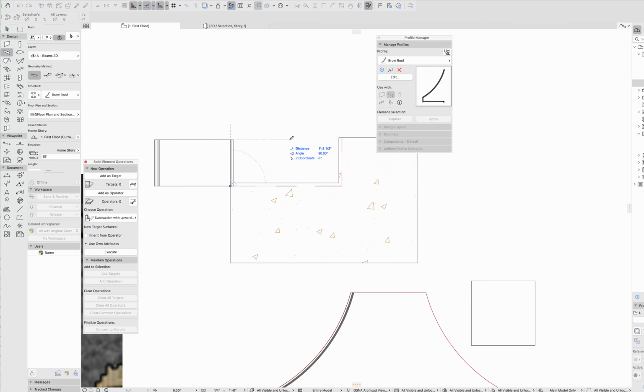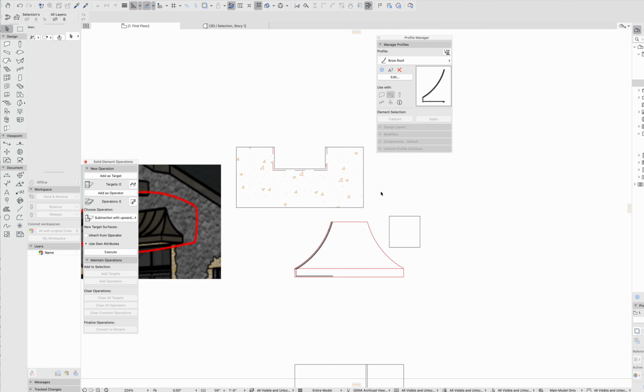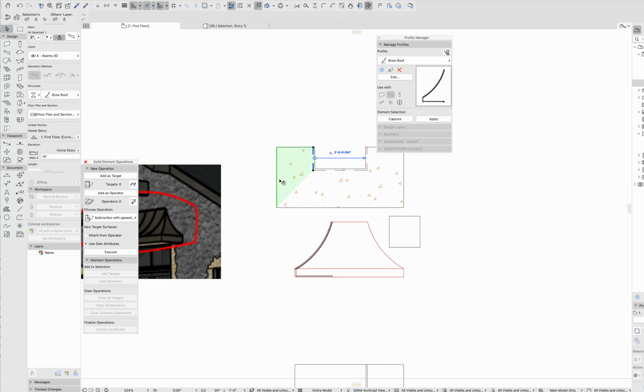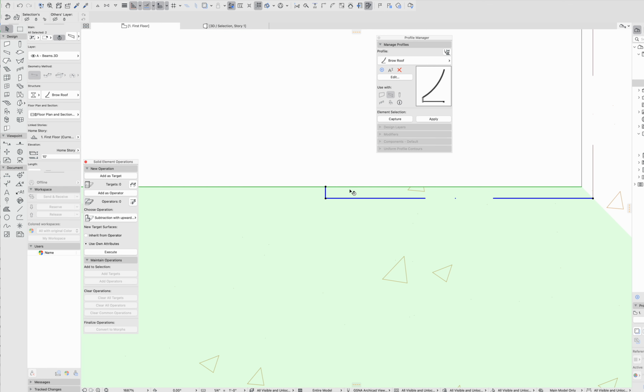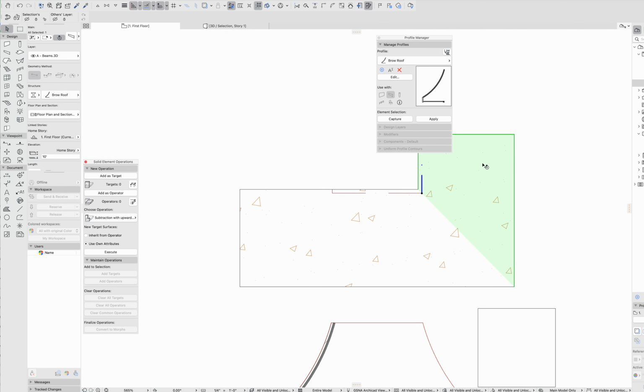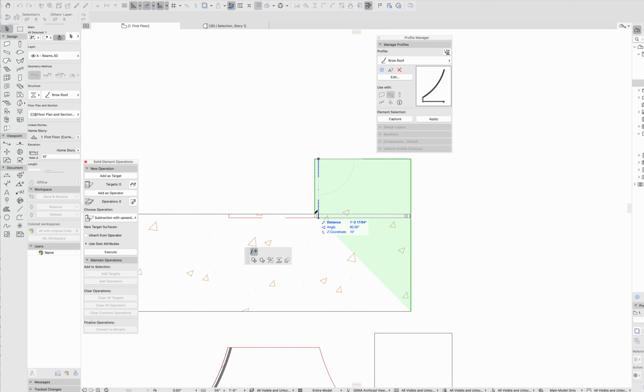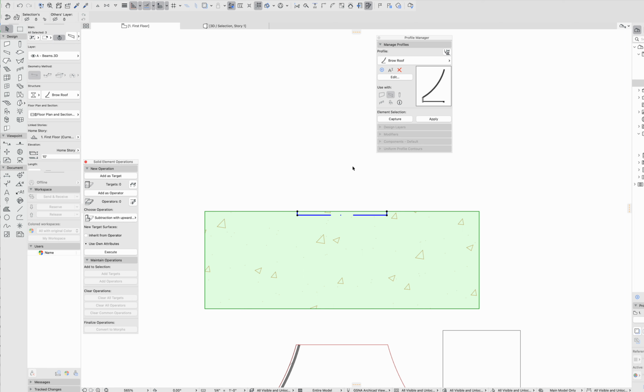And because these are beams, they're really easy to manipulate after the fact. So let's go ahead and grab these and put this right here so we can see exactly how wide that needs to be. We'll put this one right there. There's our overall width. And then these can come all the way back to here. They do have to have some length. Obviously they can't be zero length, but they can come back to meet the back top edge of essentially right here where that roof meets the wall above. And if this does need to set into the wall so that it's flush right here, you could do that and then just trim it out with the walls as the operator that they're intersecting with.